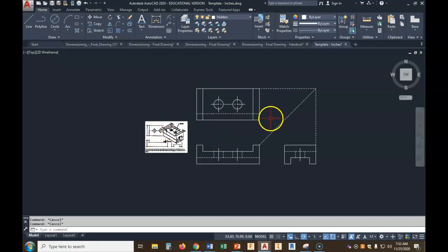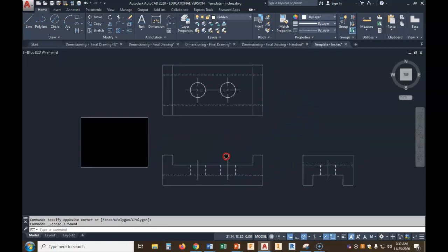Copy will work. You can use whatever you want to use. I'm just going to use this. I'm going to hover here, drag down, 0.5, all the way across, get my X. There we go. So there's the multi-view drawn. Let's get rid of our miter line. Okay? Pretty quick, pretty simple.